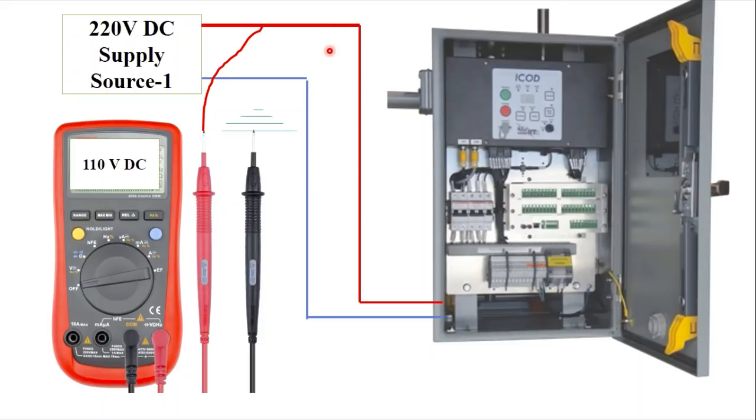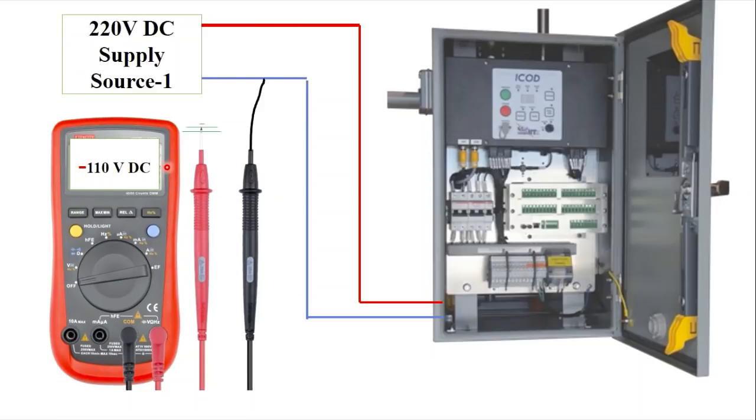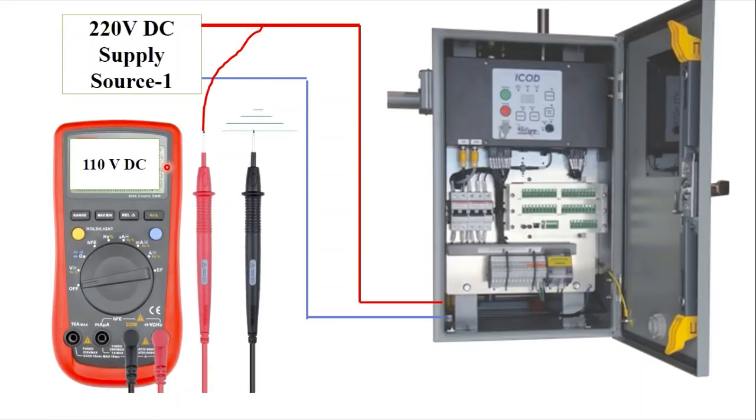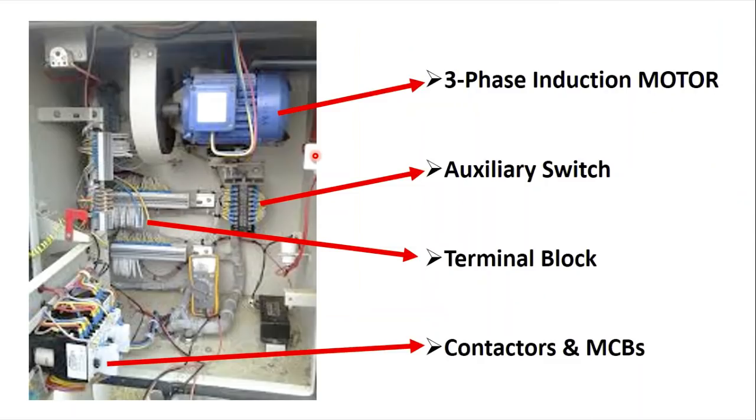Okay, so the same thing if it happens with the negative wire, if this negative wire is directly grounded, then in that condition also it will show minus 0 volt DC. So here you found by this way that there is a fault in this positive lead, or there is a fault in this negative lead. So if you have identified that there is a fault in this or this, then you have to go further. Then how would you go further?